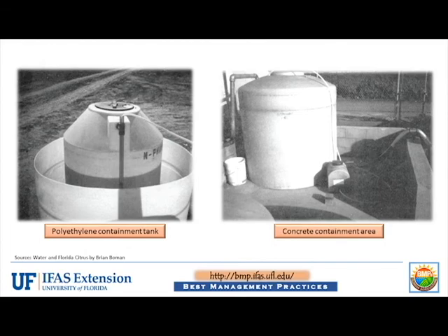State law requires chemical tanks to be placed in containment structures if hazardous chemicals such as pesticides are stored. Containment can be achieved by construction of a watertight concrete pad with concrete block walls sufficiently large to hold 1.5 times the capacity of the chemical tank in the event of tank failure. Polyethylene soil liners can be used under the tank in permeable soil areas or where toxic chemicals are being used.